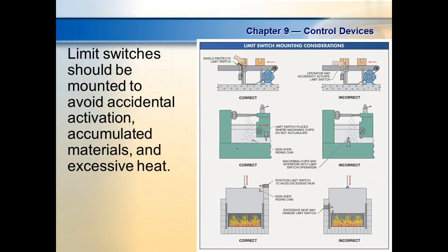Limit switches should not be mounted where they risk accidental activation, accumulation of material, and excess heat. So here they're showing us correct and incorrect. The top one says that's correct. The bottom one says that's incorrect. And you'll see what we're talking about.